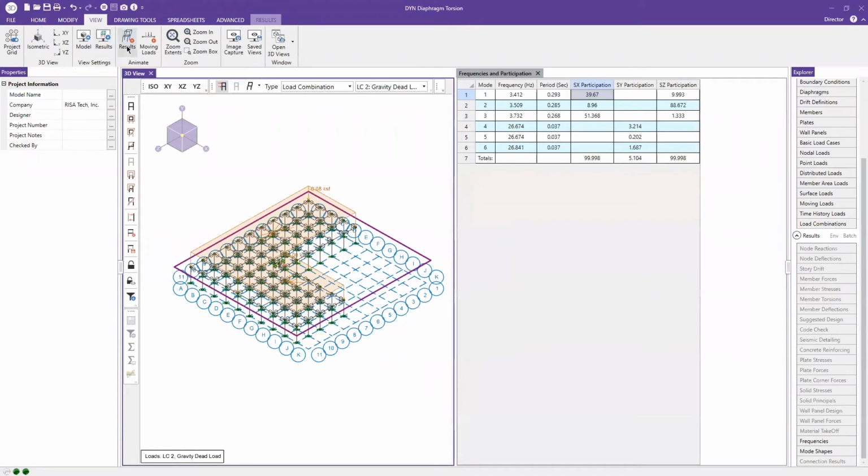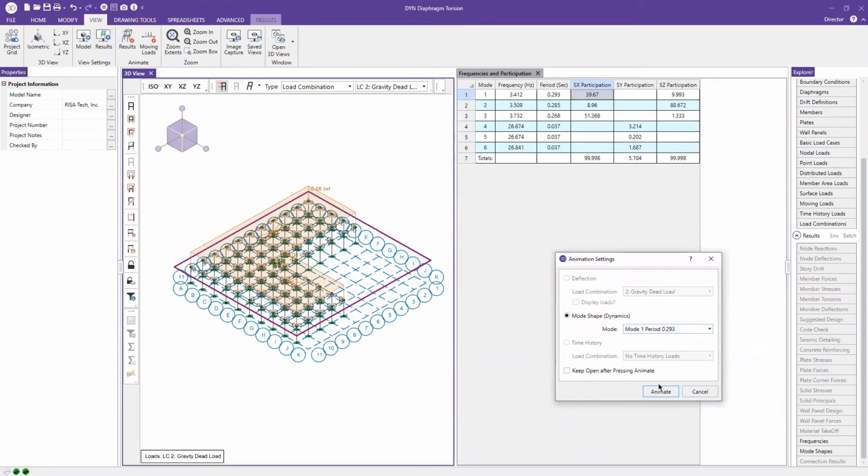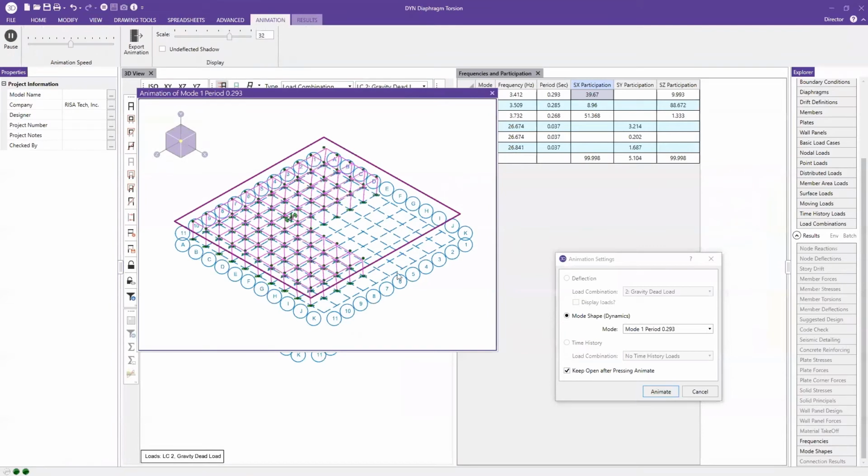Now we can do the same thing and review the mode shapes here. So let's go to our View and the results, and see how mode shape 1 looks. As you can see, our mode shape 1 is a torsional mode. This mode shape was not possible to capture if you use a lumped mass, because that doesn't have the rotational mass linked to it. It can only move in a single direction. And if we check mode shape 2, this is pretty similar to the previous one. It's just a lateral movement. And if we display mode shape 3, we can see that it's another torsional mode.